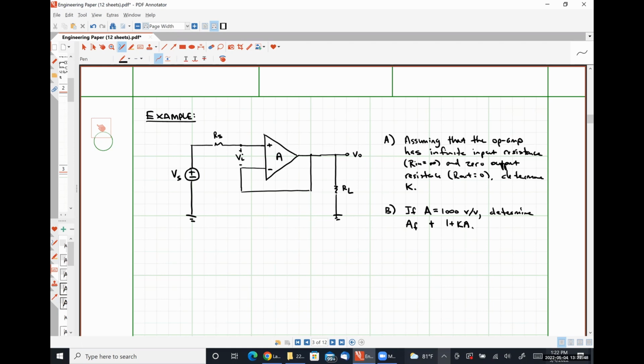So what we are going to need to do to apply the techniques that we're going to use in this class is represent our op amp by its practical model, right? The practical op amp model had across its input ports an input impedance Rin, which in this case is an open circuit.